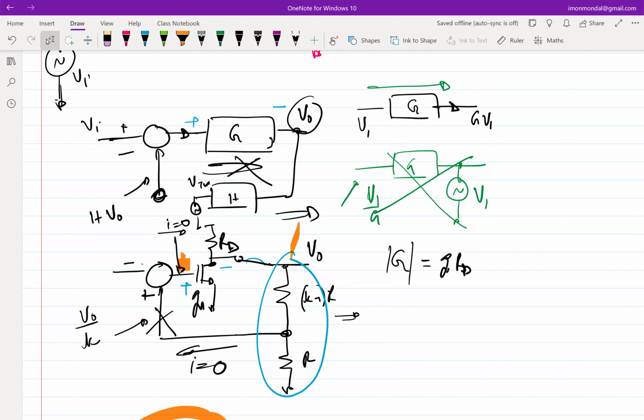Yes. Right, we have to. Even though I am only dealing with small signal, the inherent assumption is that bias has to be provided, right? So I laid out this architecture because I know how to provide the bias for a common source amplifier, and the common source amplifier bias is generally provided by putting a VDD on top, right? But it's not necessary that this is the only architecture. Whatever you are suggesting can also be done by simply replacing the RD with a current source. Right, I can put a current source on top.